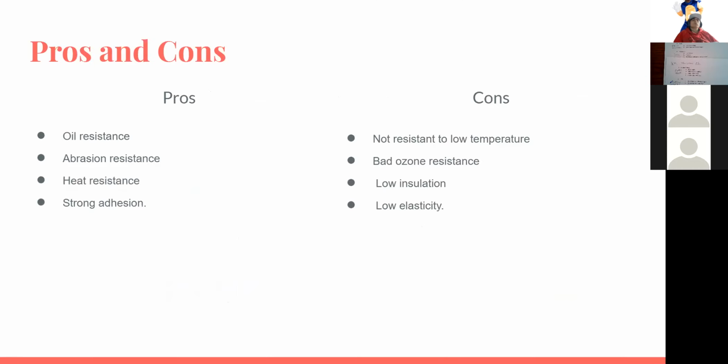Pros and cons. Pros: it's oil resistant, abrasion resistant, heat resistant, and has strong adhesion. The cons are that it's not resilient to low temperature, it has bad ozone resistance, low insulation, and low elasticity.